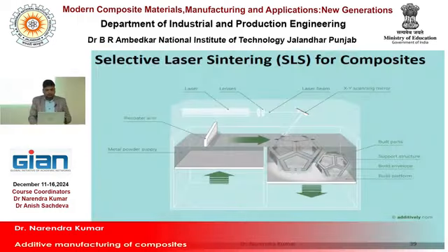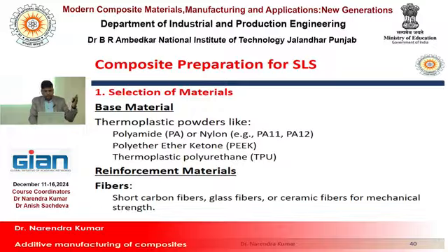Here we use material in powder form, so we can select polyamide, polyether ketone, I think PEEK. Nowadays PEEK is a very hot topic, because it has the capability to sustain 300 to 400 degrees centigrade, and it has a lot of application in biomedical engineering.